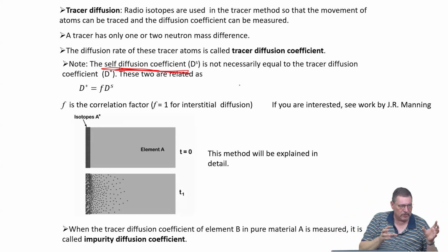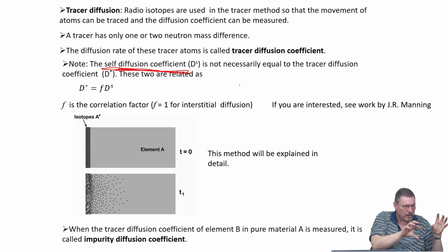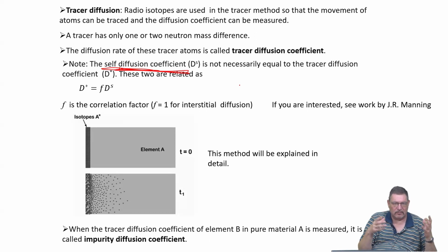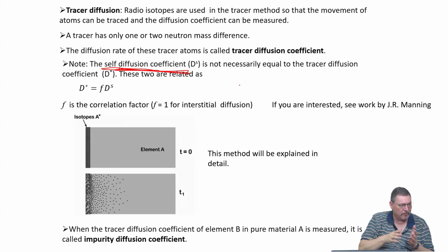If you have substitutional diffusion, there might be very different ways how the vacancy can interact on this lattice side or on this lattice side with the atom you are now observing. And this is called a correlation, causing a correlation factor, causing cross terms in the diffusion matrix. And so the correlation between random walk diffusion distance and real diffusion distance after n jumps for substitutional diffusions in real lattices will not be 1. And this difference, which is not 1, will be the so-called correlation factor.